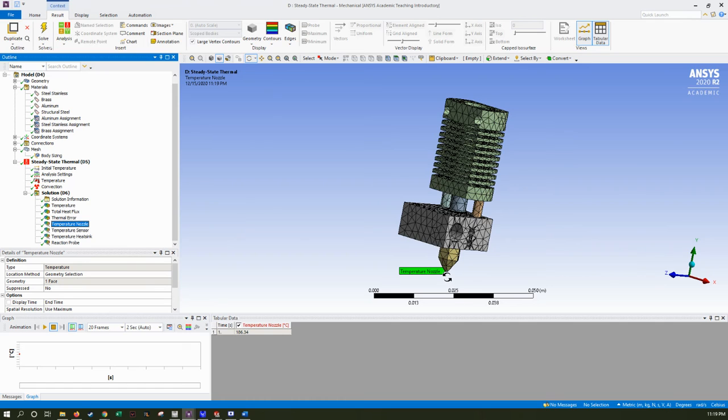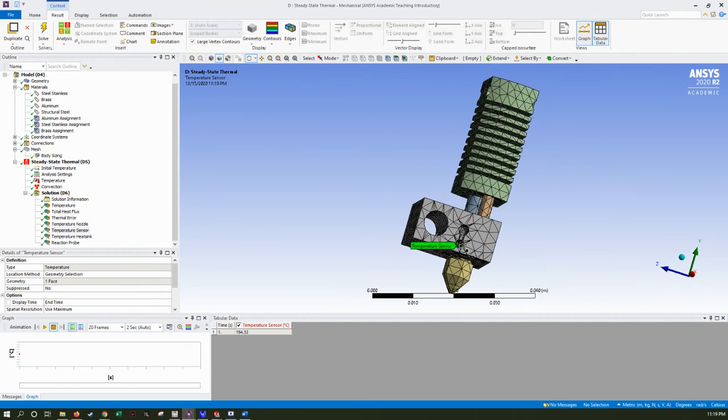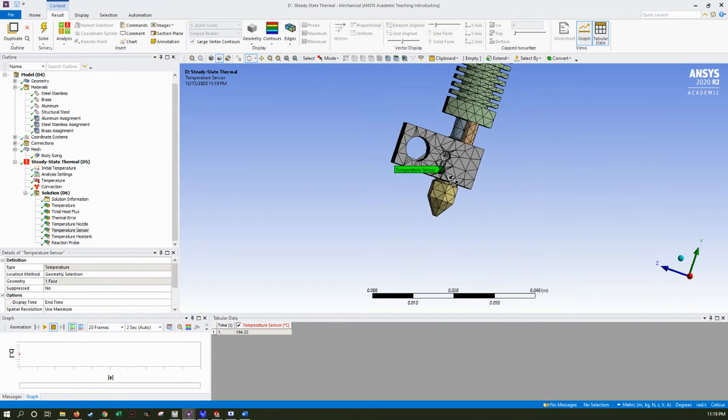The probes were also added at the nozzle and around where the sensor is. This shows the difference between how the system would read the temperature to the rest of the 3D printer, saying, hey, the nozzle is this hot, versus how hot the nozzle actually is. And there seemed to be about a 10-degree difference between them, which, depending on what filament you're printing in, can be significant.